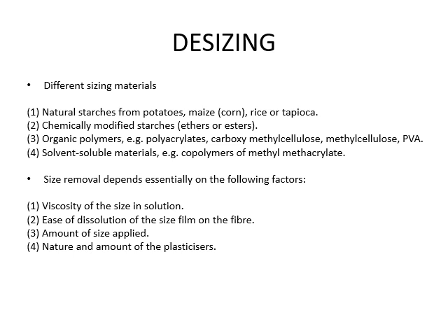Then the nature and amount of the plasticizers used. These plasticizers are nothing but polymers. They form a film over the fiber. And if the plasticizer amount is higher, penetration of desizing chemical for the desizing of these starches is very lengthy, and they cannot reach the thickening agents, and definitely removal will become more difficult. So optimum concentration of plasticizer is the basic need.